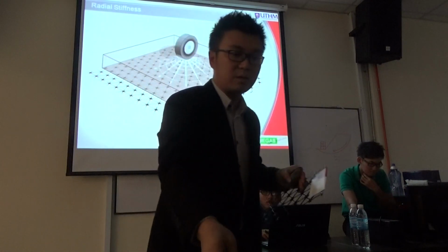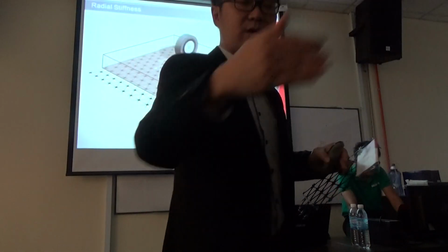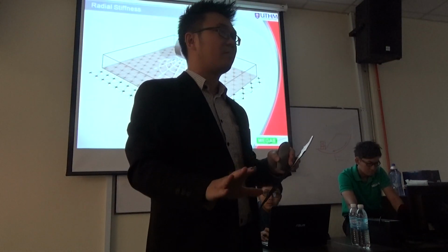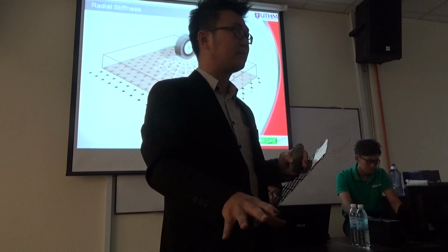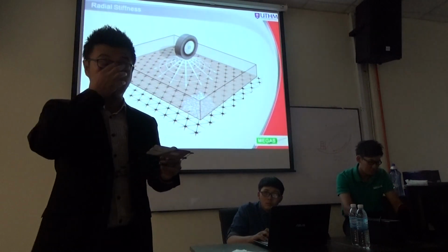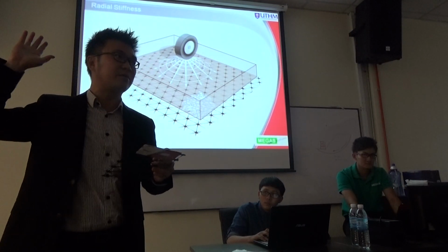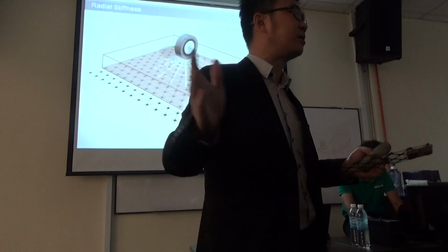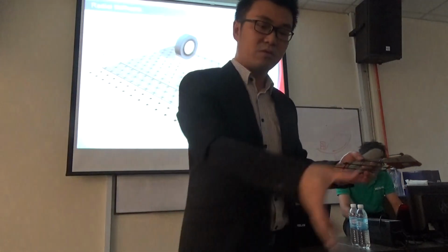If we use it for a normal pavement road, for example the road outside, normally the car will go this way or this way. So biaxial is maybe okay already. But in terms of load distribution, this is still not perfect. To make it much better, for example for a car park, where the car can go this way, this way, any way, or for a working platform in a fabrication yard, where machinery can go any way.